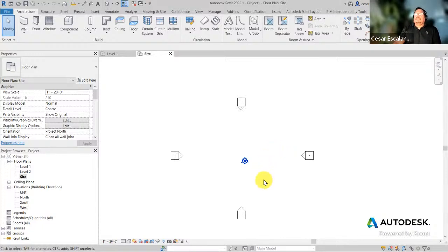The problem is when consultants start at different points in time and these projects are not aligned. And once you anchor them, they are floating in different locations because they have different start points. And so when that happens, the best strategy is to use established shared coordinates. And so I'm going to switch to a 3D view.